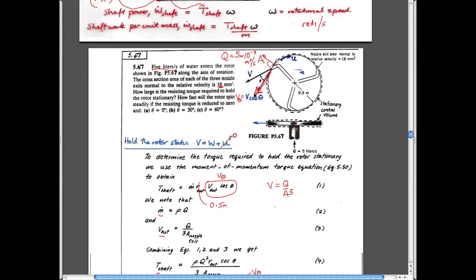So that's it. So we've talked about momentum, we've talked about linear momentum, we've talked about rotational momentum. They're analogous in many ways. I think the interesting thing about them, if there is something interesting about them, is this idea of work that you get out of it. For the sprinkler, both of these two end-member cases, we get no work. You hold it static, it's not moving, no power. You allow it to rotate freely, no power either. Somewhere in between, if you hook an armature up to it, you're able to get work out of it, and you can calculate what that middle point value should be as well.